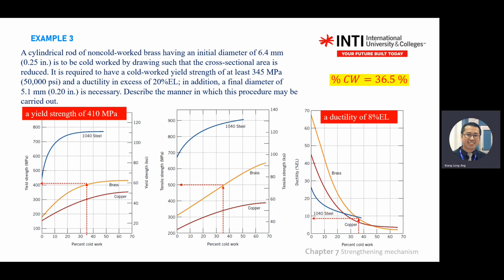Then, if you do previously 36.5, your stress passes, but your elongation percentage fails. How do you make this pass? Try to think. Now your customer needs this one. If you do this process, you get the tensile yield strength pass already, and more than what the customer wants.